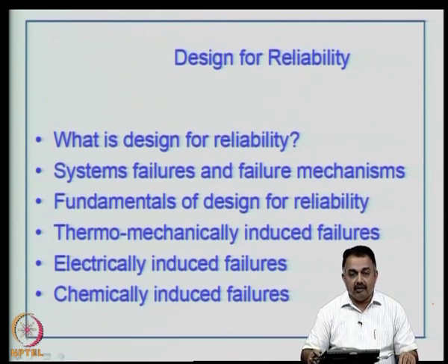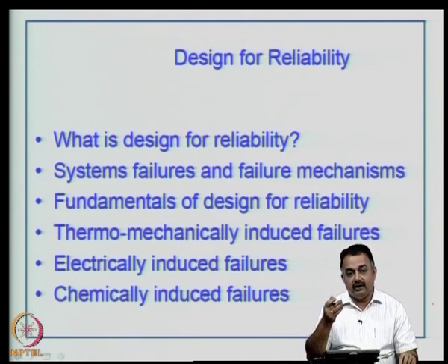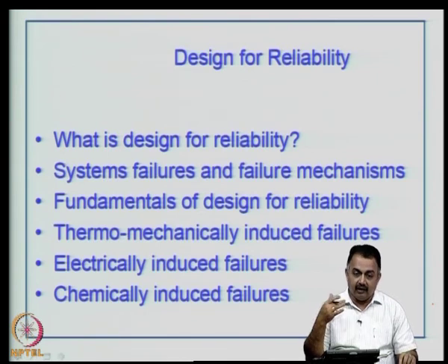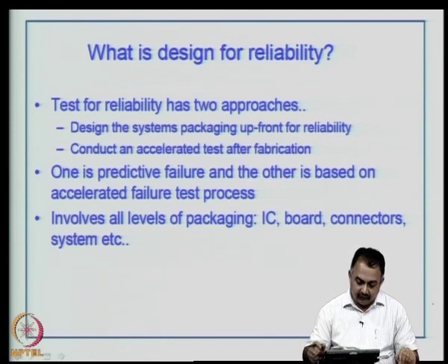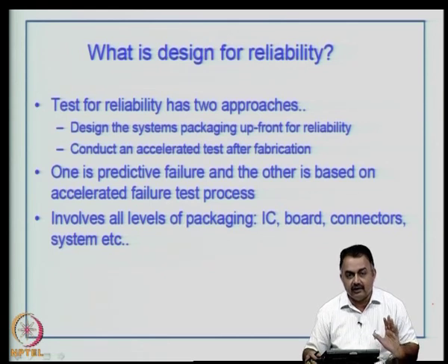Fundamentals of design for reliability: you need to understand most failures are thermomechanically induced failures. There can be electrically induced failures and chemically induced failures, but all failures, whether chemically induced or mechanically induced, will end up as an electrical failure, right. So, test for reliability has two approaches. Design the system's packaging upfront for reliability. So, look at these considerations.